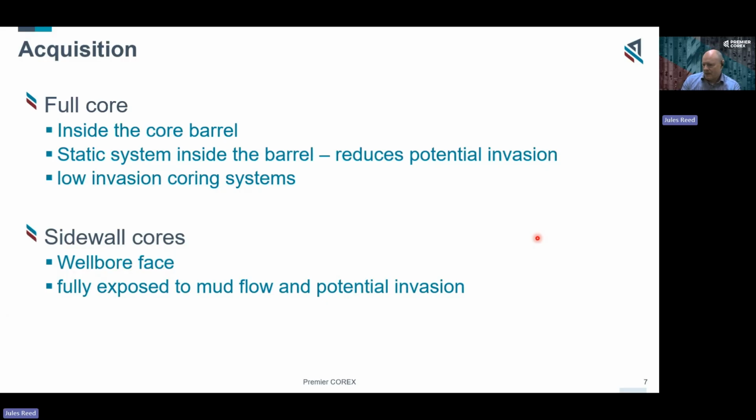As you core down, the core is being pushed up inside the core barrel, and so the core becomes contained in the core barrel, and once it's in the core barrel, it's less exposed to the mud system and to mud invasion, because inside the barrel you then have a relatively static system of the fluid.